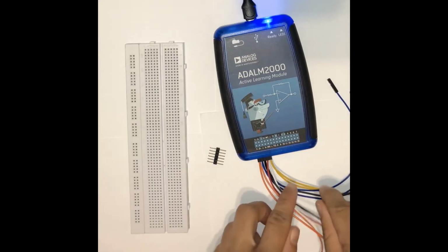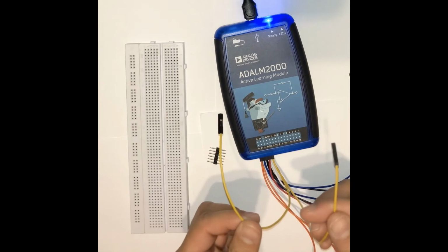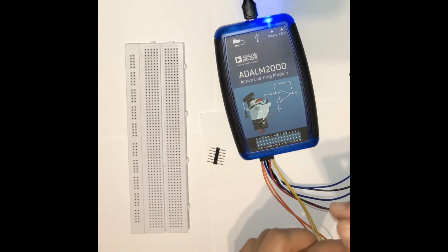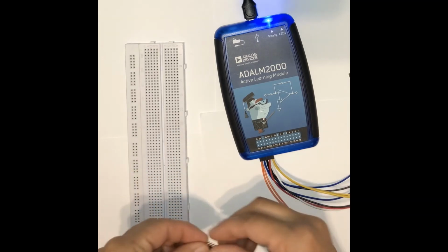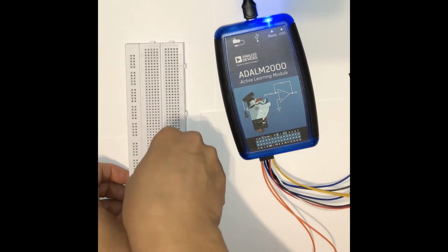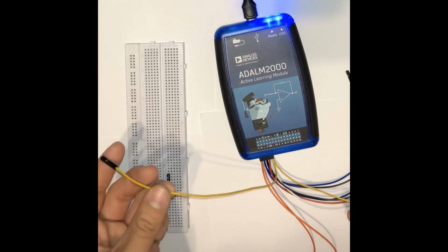From the previous video, we know that the purpose of the signal generator is to produce signals of varying characteristics necessary to analyze a circuit. The signal generator capability is demonstrated by use of the yellow wires. These are labeled W1 and W2 on the pinout board. So by simply placing either of the wires onto the breadboard through use of a header in this case, we can enable a signal onto the circuit.